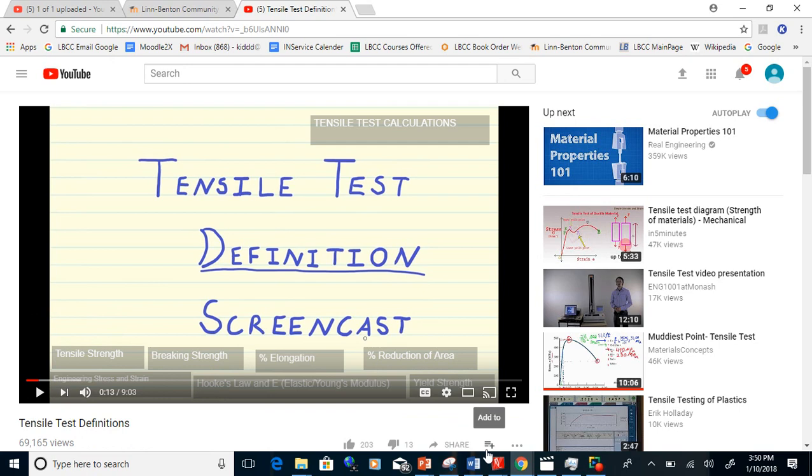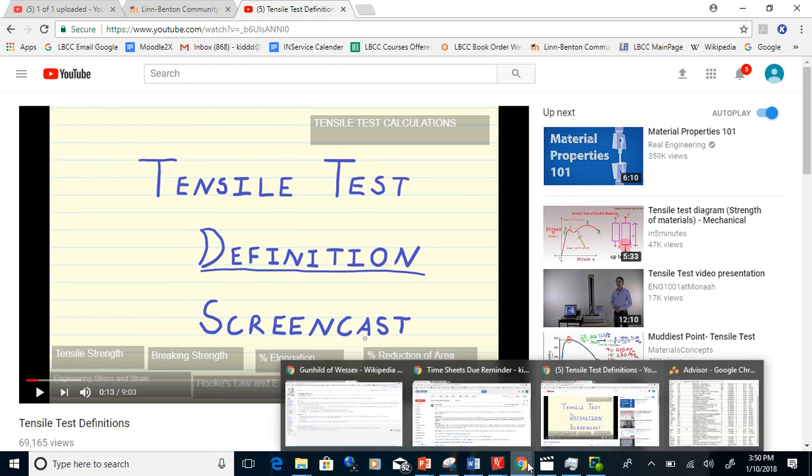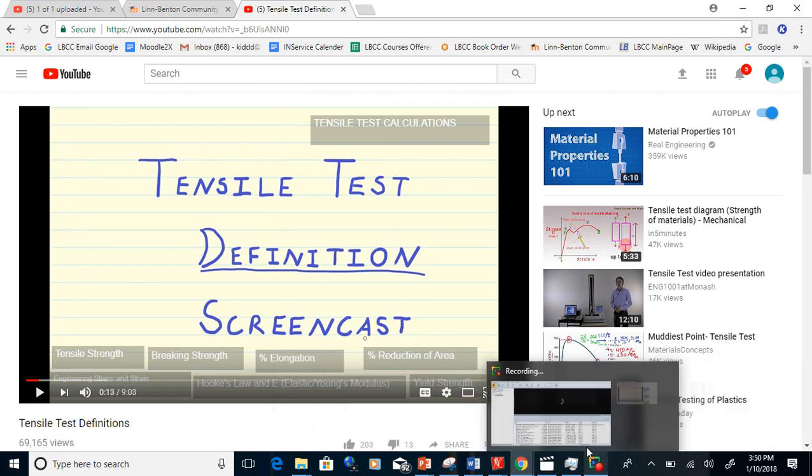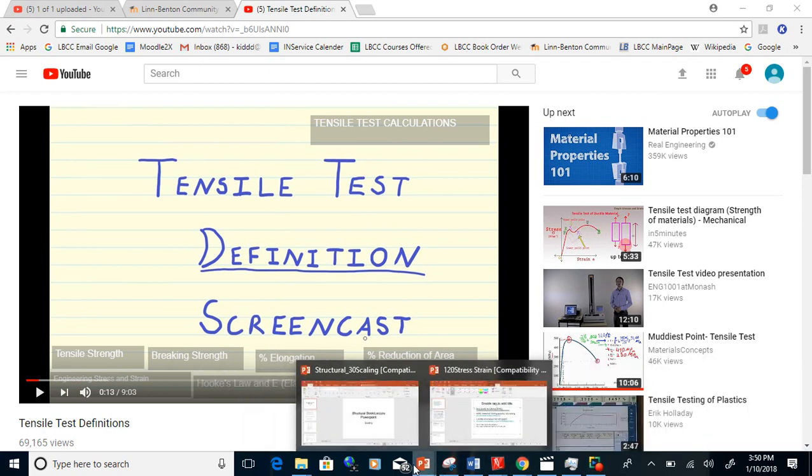The atomic properties, there's just more fractures in there, more crystal imperfections. It just happens to be the weakest spot. It'd be different every time you ran the test. Oh, the same material will act different spots? Yeah, sure. It just depends on those crystals, they're not perfect. That makes sense, not every single one is gonna be exactly the same, so the neck is gonna occur wherever it happens to be weakest.